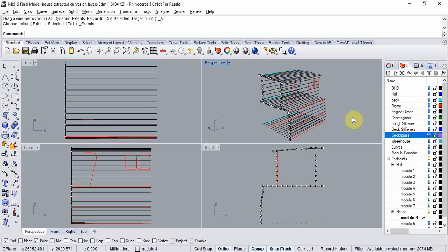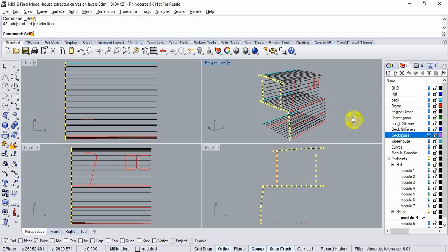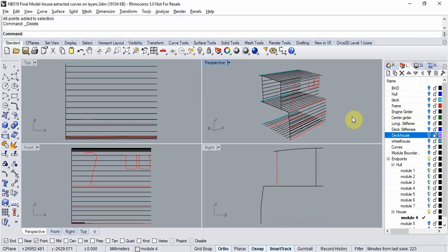Moving back into Rhino, we can now insert all of our Maestro nodes into our model. But first, let's delete all the points we previously created so we don't wind up with duplicates. We'll simply select the points and remove them, and then use the points command to insert the Maestro nodes. Where exactly they will come in will depend on which view is active when we issue the points command. Using the front window, we'll put the points in the correct orientation. If when they're imported you see that they show up in an unexpected location, you can simply hit Ctrl-Z to undo the operation, change the window, and try again.